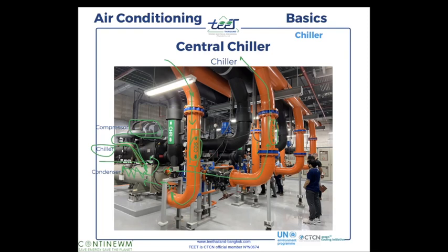And here we have the evaporator. The evaporator will release the pressure on the gas. Remember, what's happening here is exactly the same, but instead of having the coil inside the air, we have the coil inside water. And the water coming here, CHR, is chilled water returning from the AHU, from the FCU, returning from all the systems that you have in the building.